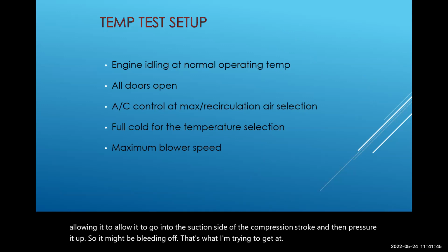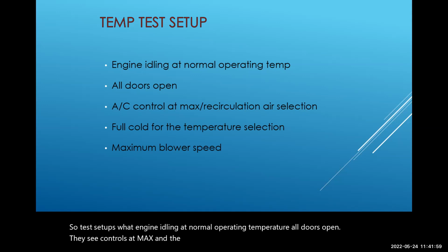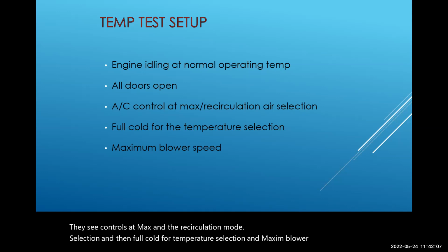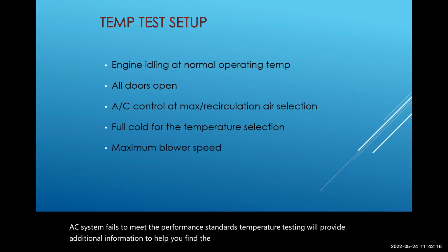So test setup: engine idling at normal operating temperature, all doors open, AC controls at max, recirculation mode for air selection, and then full cold for temperature selection and maximum blower speed. So when the AC system fails to meet the performance standards, temperature testing will provide additional information to help you find the root cause. This is the vehicle setup for a temperature drop test.